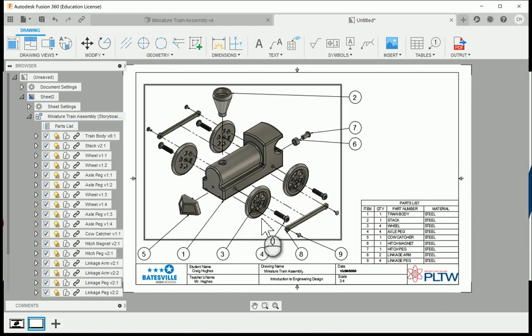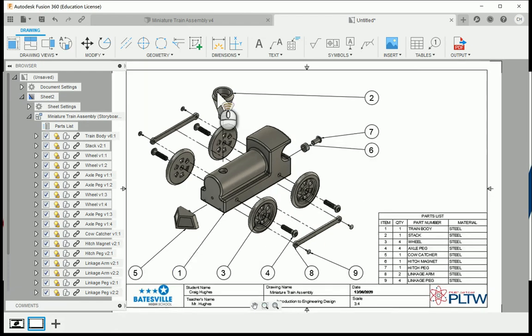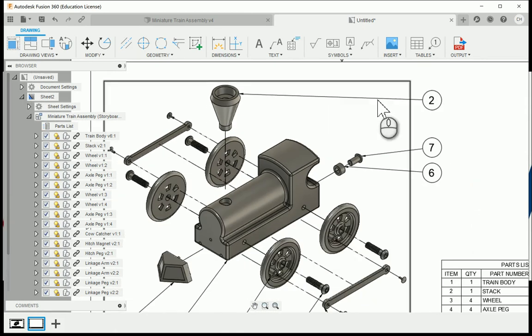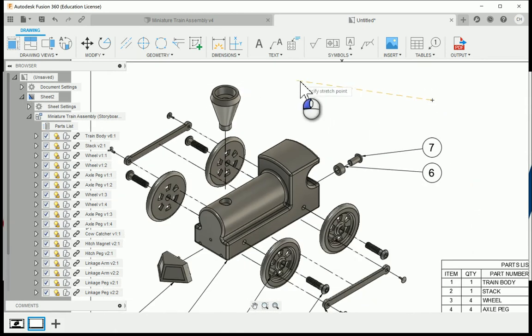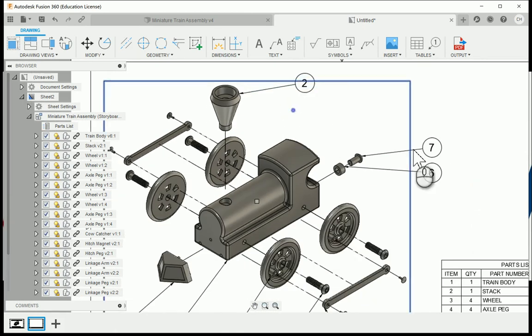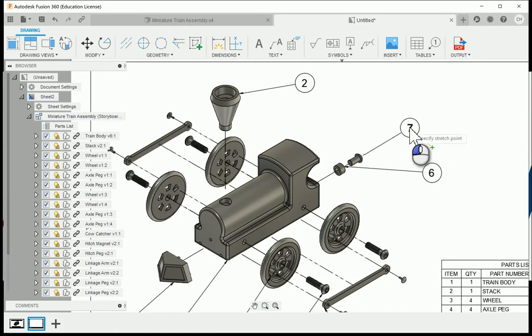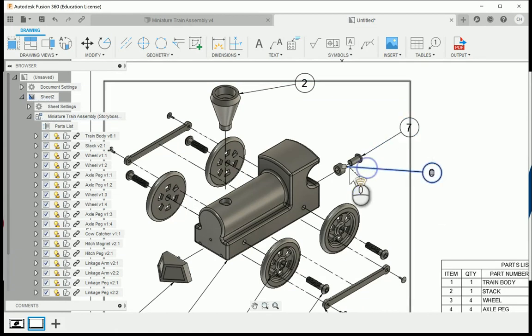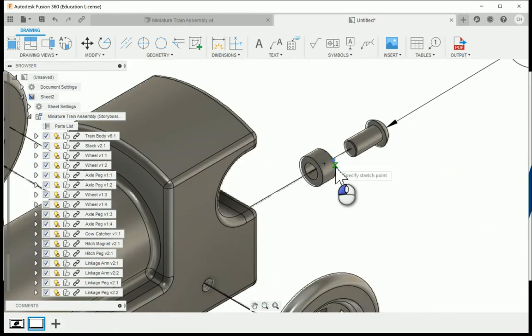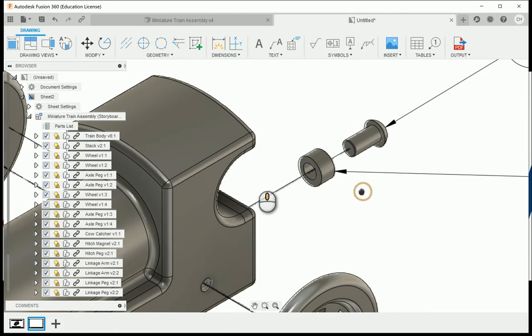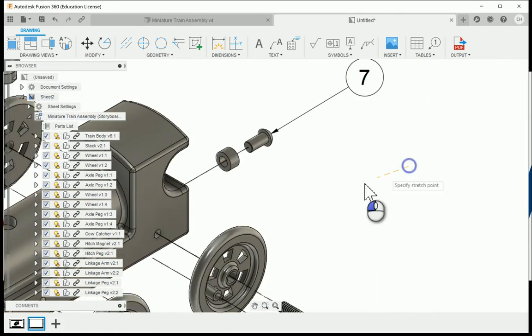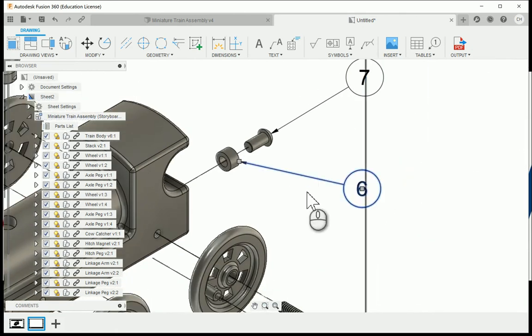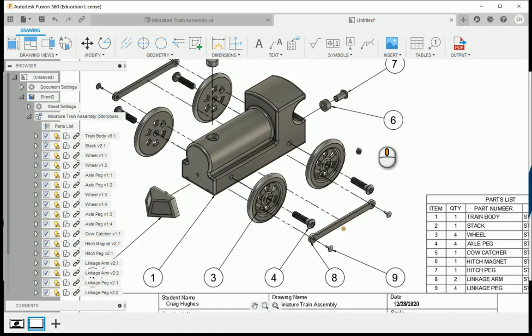And the only other thing we want to check here is, do we have all the parts being represented, but also some of the balloons that are showing up here as well. Like the 2 is really far away, so I'm going to bring it a little closer. And I'm just going to spread these apart a little bit more. The other thing is, I may want to try to pick along the arrow points. Maybe some of these points need a little bit better positioning.